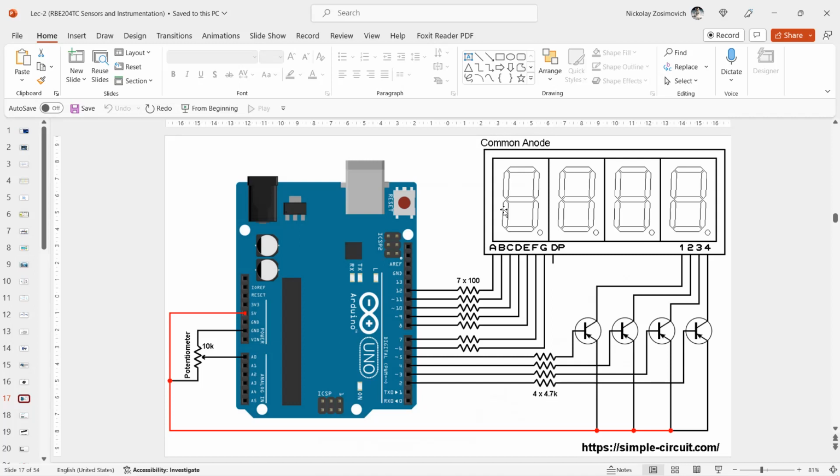What does it mean? It means a maximum sampling rate of 10 kilohertz, depending on how the sampling routine is configured and implemented. But you should note that this is largely caused by the implementation of functions like analogRead in the Arduino environment and library.